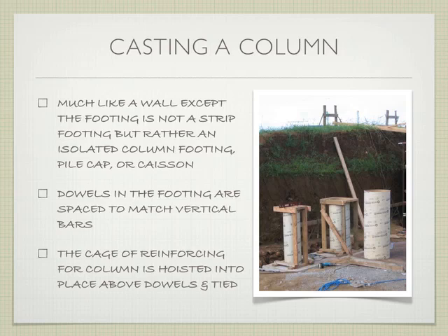So let's use the book drop out by the pond as a good example. It's an exterior wall that's providing access for them to unload the books, but it's going to stay exposed to the exterior. If we use something like this to form up that particular piece of wall, this would be on the outside. It would be exposed. They'd have to clad it with something and maintain that cladding. If it's outside like that and you want the concrete exposed, because it's a retaining wall or something like that, you form it up with wood and then remove the wood, and the concrete is its own finish.